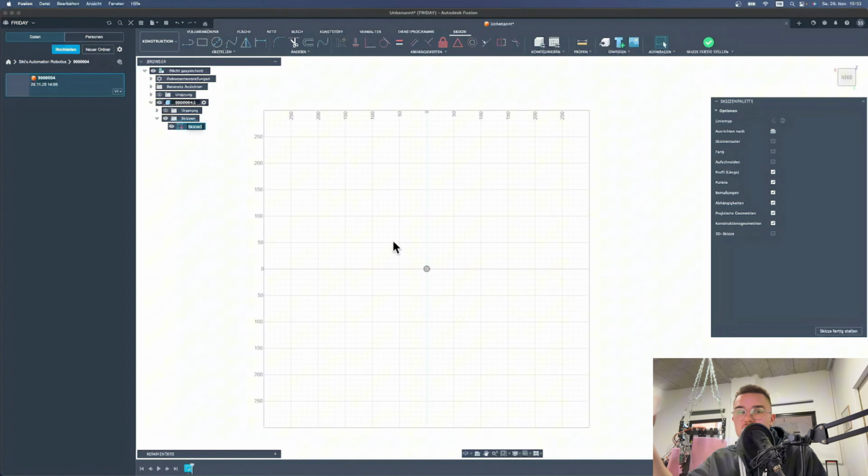You see, oh no, that hole is on the wrong dimensions, etc. On the wrong surface, for example. I need to change that. Then you need to go to that node probably and change it a little bit, change the distances, or change the hole itself. And then you are really, really proud of yourself when you give the nodes names, because you recognize better which node you need to change.